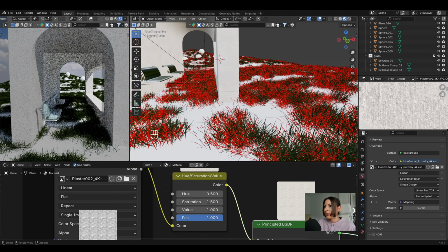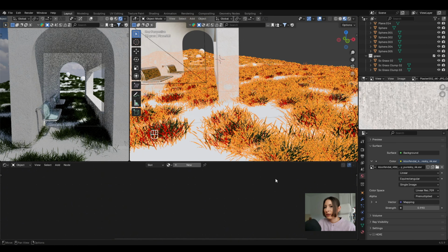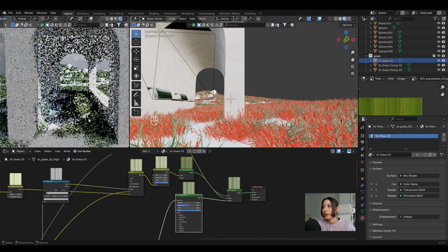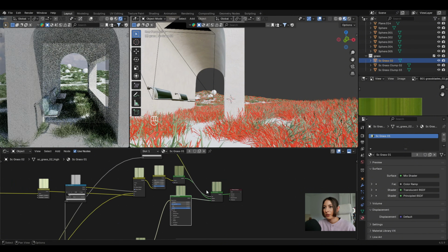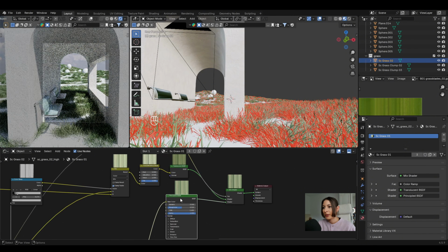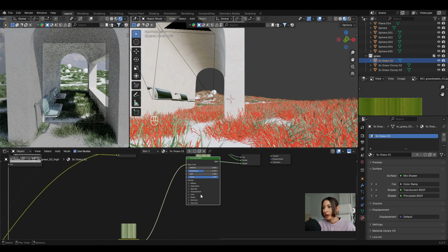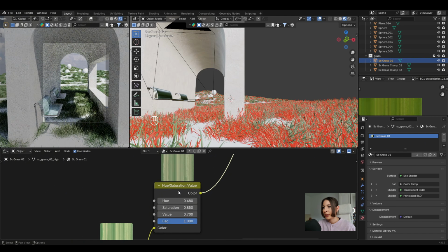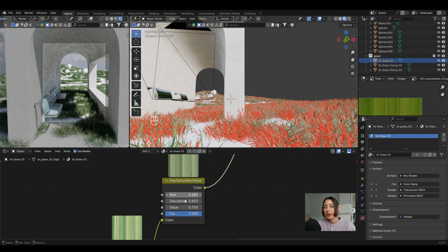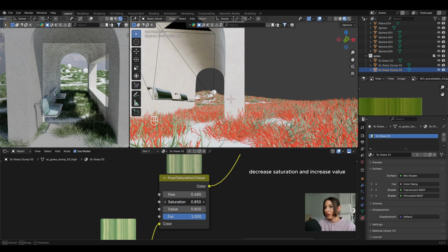And I also think the grass is not really that nice looking. You can also change the look of the grass. I think it looks too dark. So what we can do is go to the grass texture and the Principled BSDF. And if you go down, here you can see the hue and saturation and you can change these values here. And the grass looks much nicer. And also maybe not as much saturation, so 7.5 is nice.